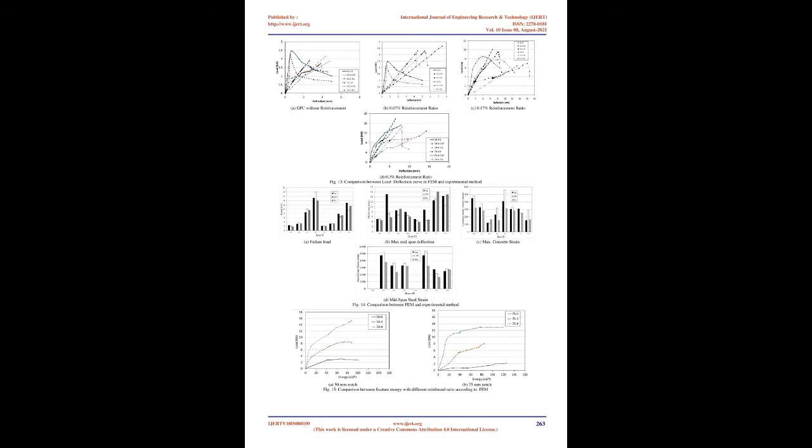Damage for traction separation law model parameters. The TSL requires concrete tensile and compressive constitutive relationship and the maximum principal stresses. The fracture parameters can be assigned to their commonly used values. The maximum principal stress in this model is based on the uniaxial unconfined compressive strength, FC, and is denoted as maximum. The steel in the finite element models was identified to be an elastic perfectly plastic material and